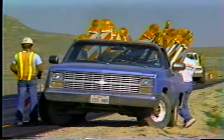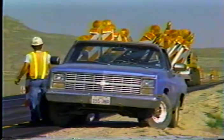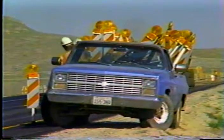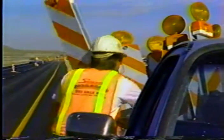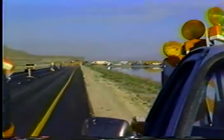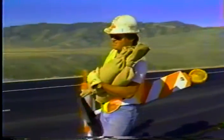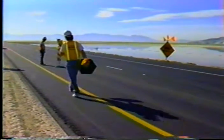The point is, the contractor must use the signs and devices specified, not what he happens to have on the truck. The devices must be made of approved materials, and they must meet the minimum standards of size, design, and color described in the MUTCD or called for in the plans. And that's all there is to selection.